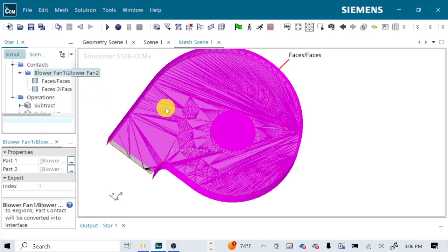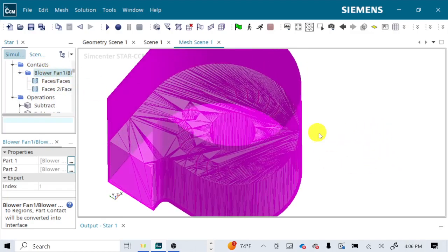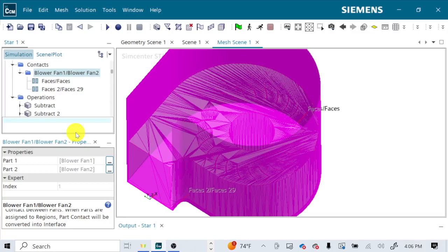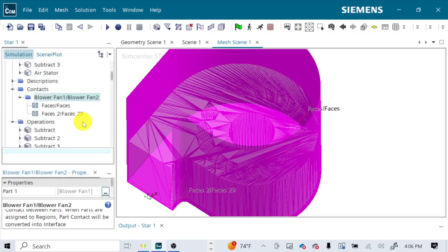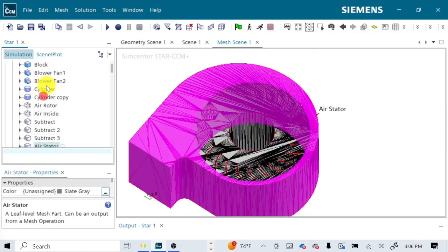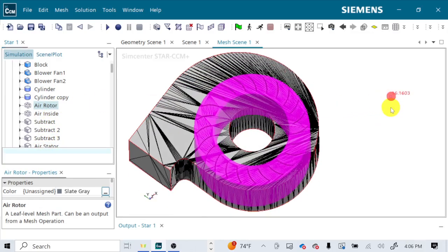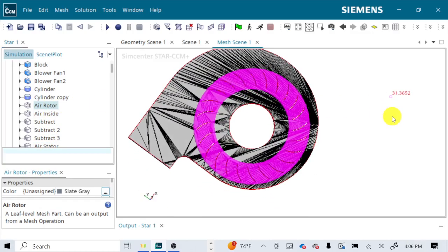We do have a couple of contacts. They don't actually matter. These are not relevant for us. So we need to do an imprint to get the ones that are relevant because we just made the connections. We just made the surfaces that we want to be touching, right? What surfaces do we need to interact? I'm just going to highlight this one because realistically, this is the only one we need.